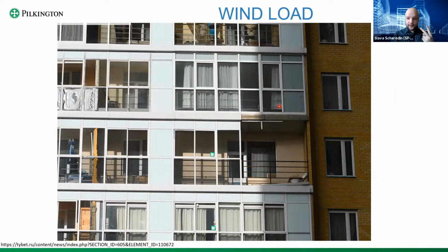That is very rare, but you need to be sure that your IG unit and the glass in it will withstand that load and will remain whole. So that is why you need the wind load, to understand whether the glass will break or not. That is called peak load. Peak meaning пиковая нагрузка in Russian, so maximum. That is in short about wind.